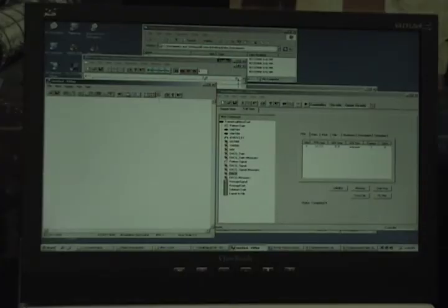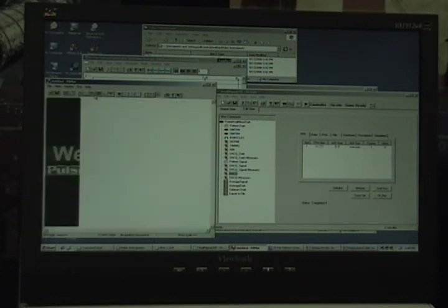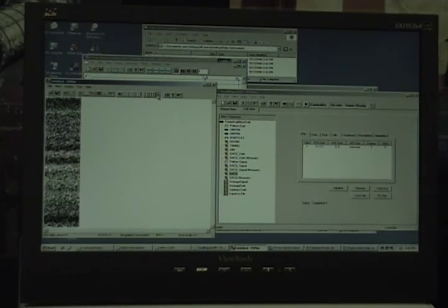Here is an example of the system's ability to acquire very small signals. This is the same test pattern, but now the signal amplitude has been attenuated down to 6 microvolts peak to peak, and the image is not moving. We acquired 2,500 frames, then averaged them together.